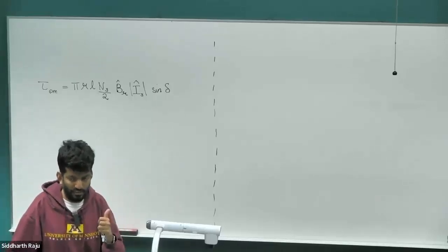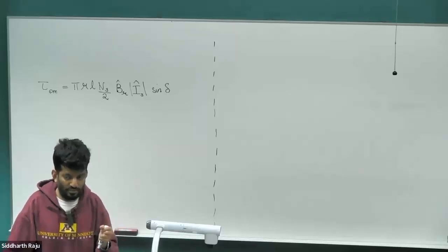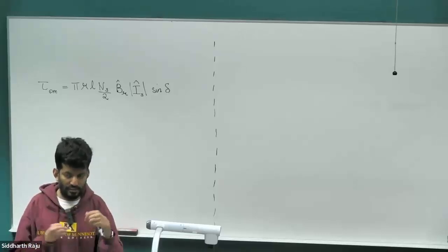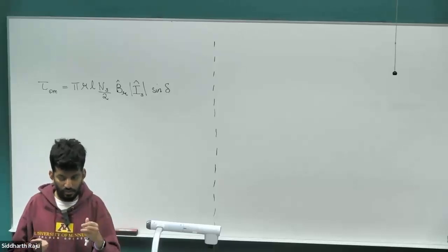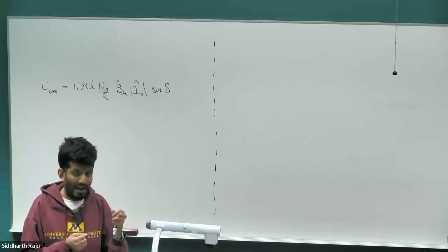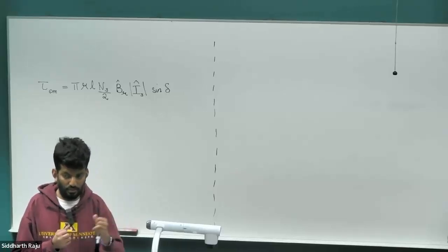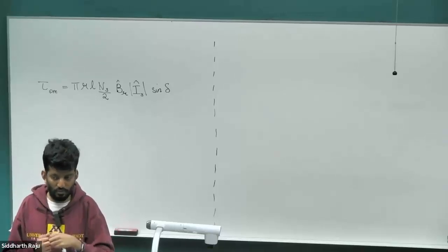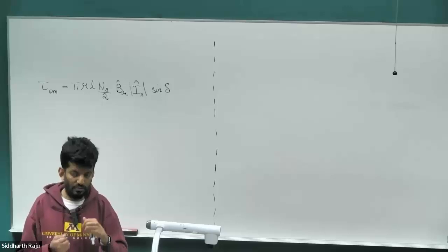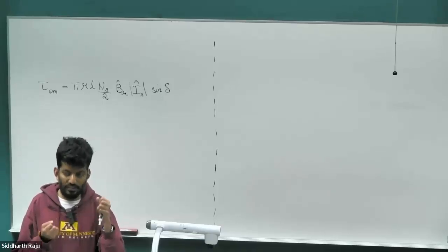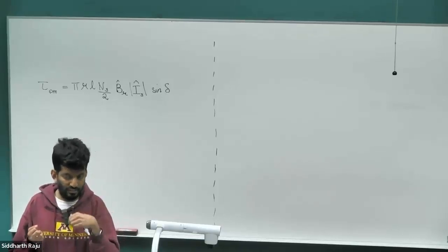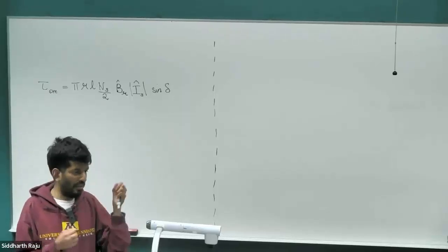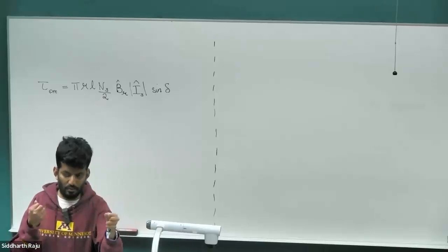That was one interpretation. The other one we saw was a geometric interpretation where we had three independent variables, and these variables can occupy every single point in the 3D space if they are truly independent. But in a balanced three-phase system, the voltages would have to be such that the sum of the voltages is zero. Even if it's an unbalanced system, if there is no neutral wire, the sum of the three currents would have to be zero. So in those cases, when the sum of three variables is equal to a constant, in this case zero, x plus y plus z equal to zero, that's an equation of a plane. And the space vector transformation is basically a rotational transformation that rotates things around.